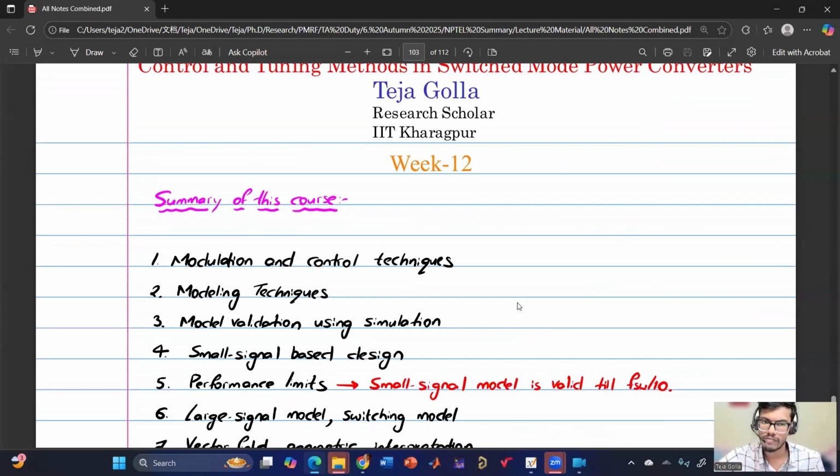So that was all about week 11, where we have identified the proportional gain for optimal recovery, as well as undershoot and peak current expressions for step up response, and proportional gain for step down response, and also dynamic voltage scaling, and how the optimal response parameters are dependent on inductance and capacitance. So if you have any queries, you can ask. I'll just quickly summarize week 12 as well.